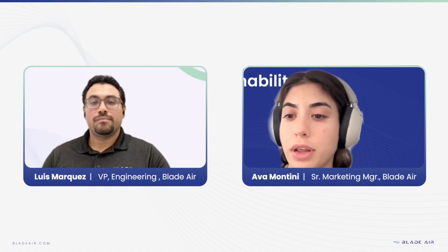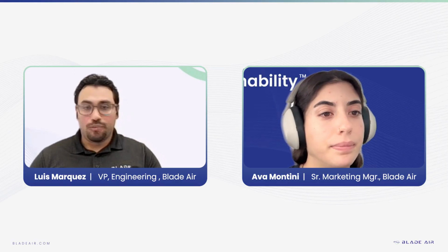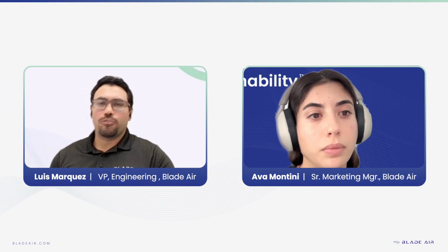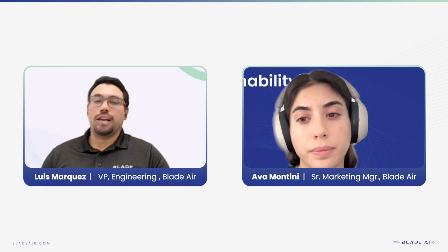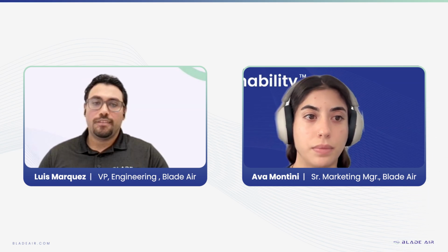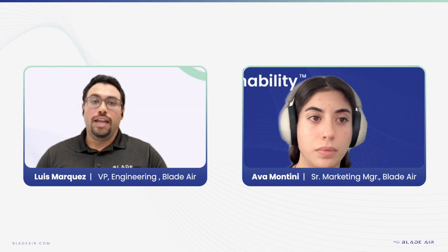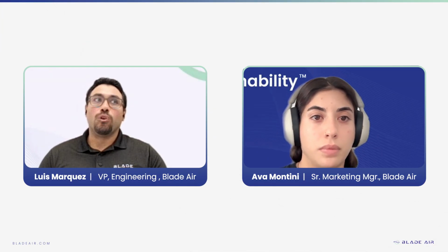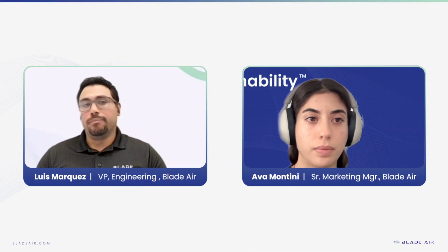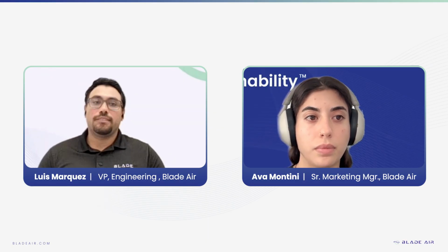As far as airflow reduction in the example, what percent was it reduced with your blade filter? That's a good question. It's off the top of my head, but it was actually, I believe, 82 or 84%. So it's a couple of percentage points higher than what I gave as 60 to 80%. It really depends on the existing system, and most spaces won't be bringing in 100% outdoor air, which I was doing in my example. So from a realistic or existing standpoint, you're more likely to be in that 60 to 80% reduction range.